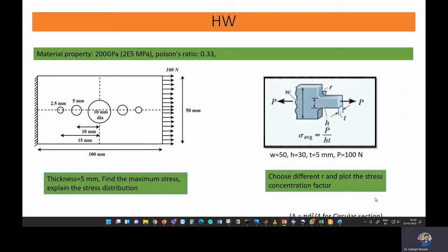Next, we'll see how we can go for nonlinear analysis for your brittle material. Now, if you want to analyze this plate as a composite plate, and you want to analyze the failure of this plate, again the failure of this plate will be brittle in nature, so you have to give the property of brittle material. If we consider a composite, then you have to provide your elastic parameter as well as your damage parameter.